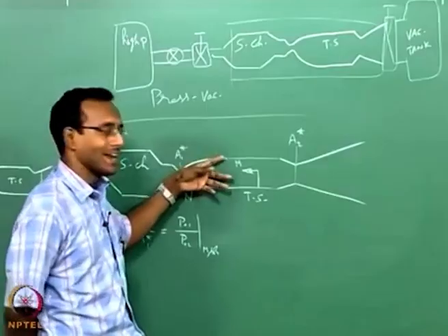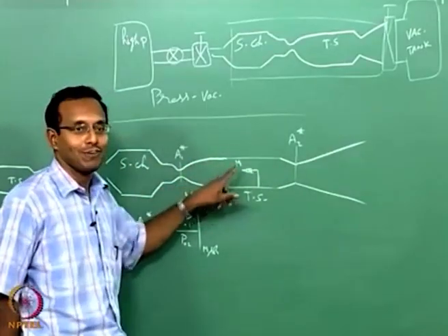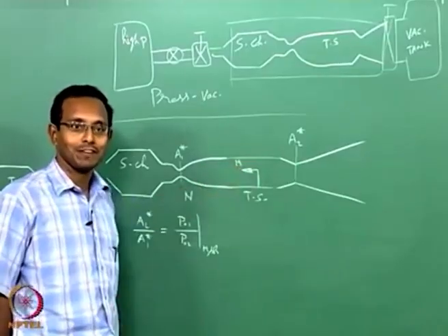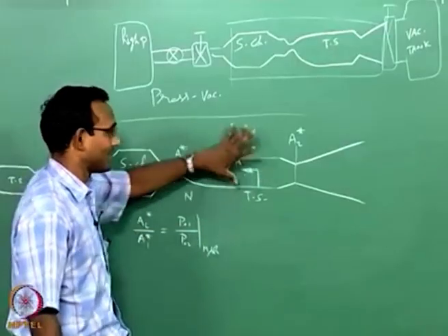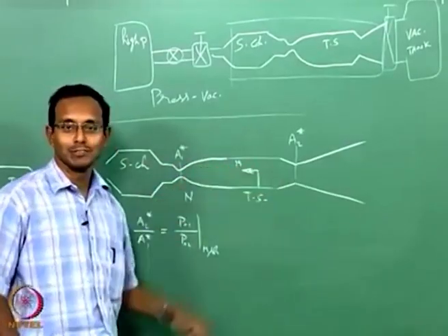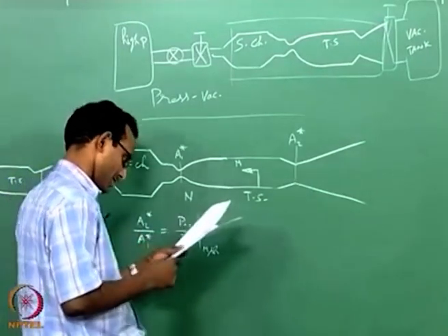And you can exactly calculate how much the area divergence should be. So, for that particular Mach number, for the particular friction factor f and the hydraulic diameter D of your test section, etc., you can calculate and put that value, and you can measure the Mach number, and it will be almost constant, whatever you expected. Okay. That is possible to do.